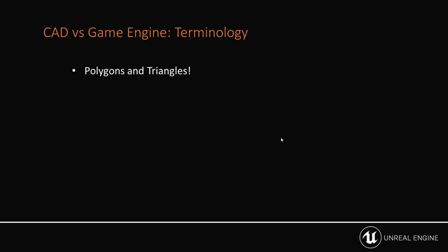In a game engine, that's always been a bit of a battle, taking that dense CAD data, dense in the sense that once it's translated to polys and tris, it can be very, very big, something that's not going to perform well in a game engine. The trick is to get something that tessellates nicely, is accurate to the CAD data, but performs well within the game engine.